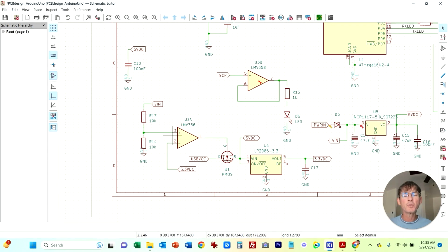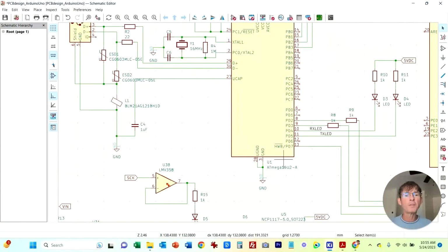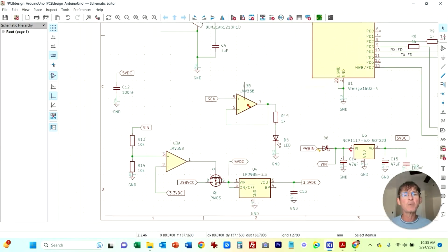It's got its 2 inputs and output, 2 inputs and output. But what we're missing is pin 4 and pin 8 are the power pins. And I forgot to add that part of the symbol. Most things have just one symbol for the entire chip, but certain things like op amps, if you have multiple ones on the same chip, it just makes it more convenient to break up that symbol.